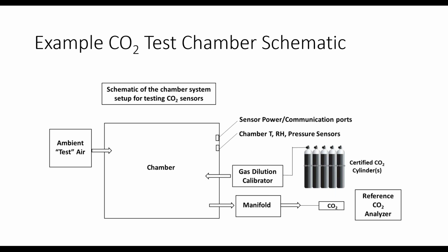Similarly with CO2, we're bringing in ambient test air. There's no real practical way that we could come up with to scrub CO2 out of the air, which is why we started at a baseline level of 450 ppm concentration of CO2 rather than a specific concentration tied to, say, the limit of detection of the reference monitor, which is extremely low in CO2. Scrubbing that amount of CO2 out of ambient air is just extremely costly.